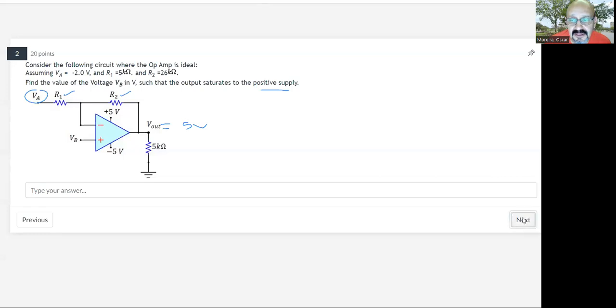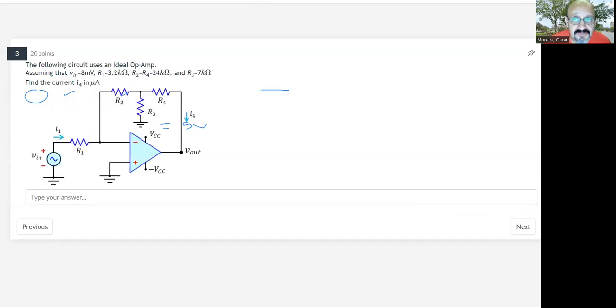No big deal. Next problem, it's a gain multiplier type of circuit in which the output voltage is a function of the feedback resistors, inverting, right? Because it's in an inverting configuration, so the gain is negative. And the reason we have this T network on the feedback is such that the ratio of resistors is not too large when the gain needs to be high.